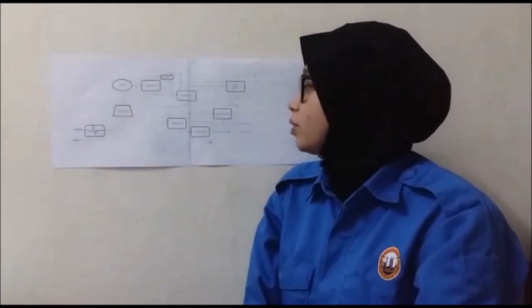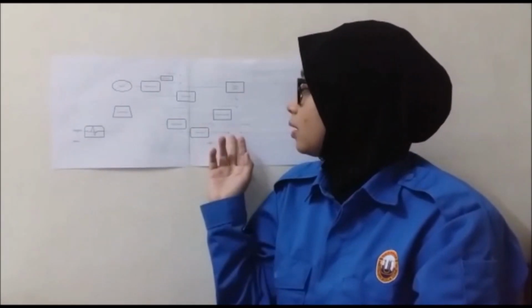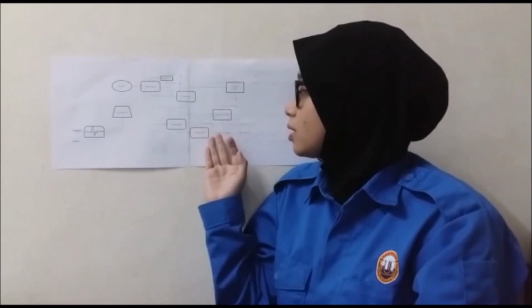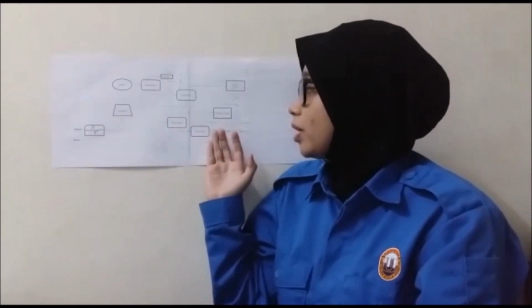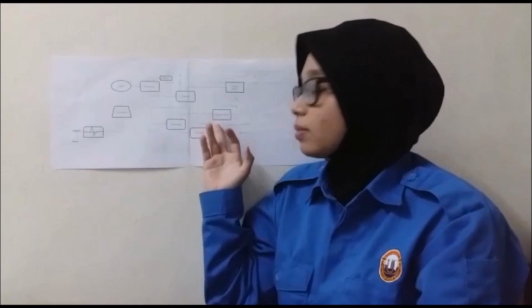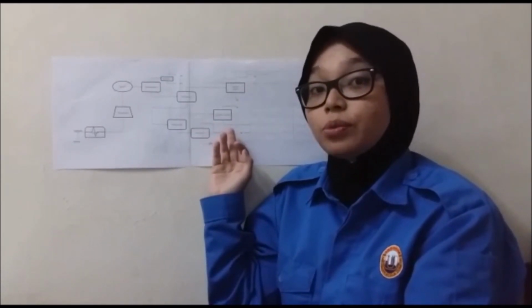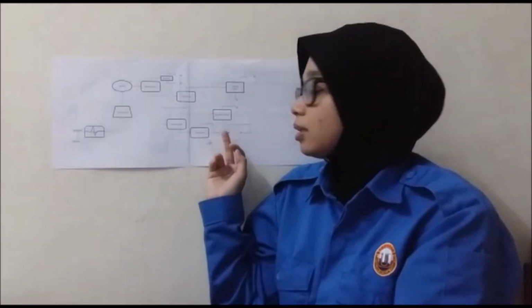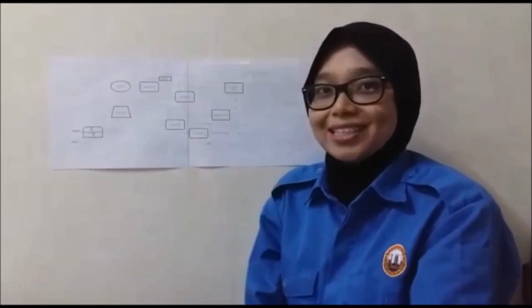For the debutanizer, the process is undertaken in the fluid catalytic plant. The function of the debutanizer is to separate the butane and lighter from the gasoline. This process will make sure the overhead stream contains 98.5% of the butane and lighter, and the overhead stream will also contain 1.5% of the pentane and the pentene. That is the end of the process.